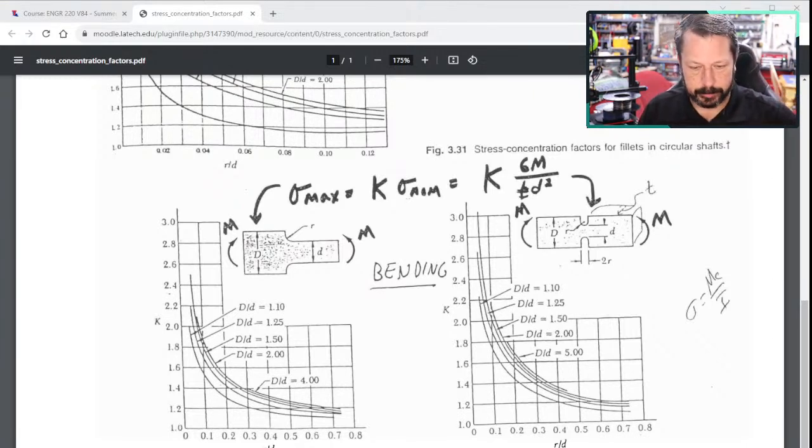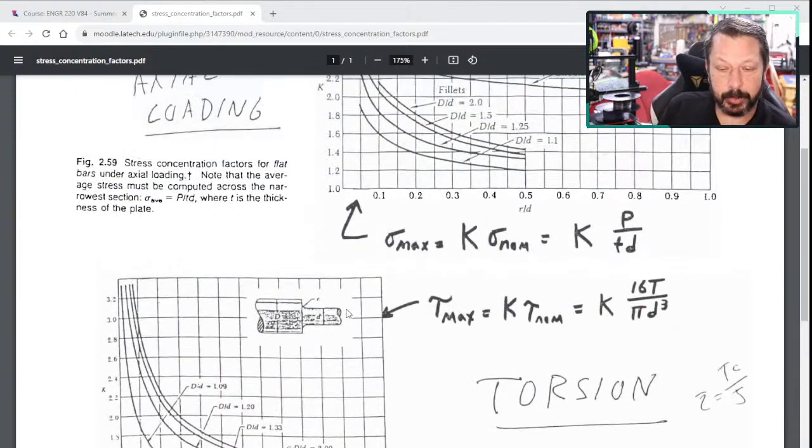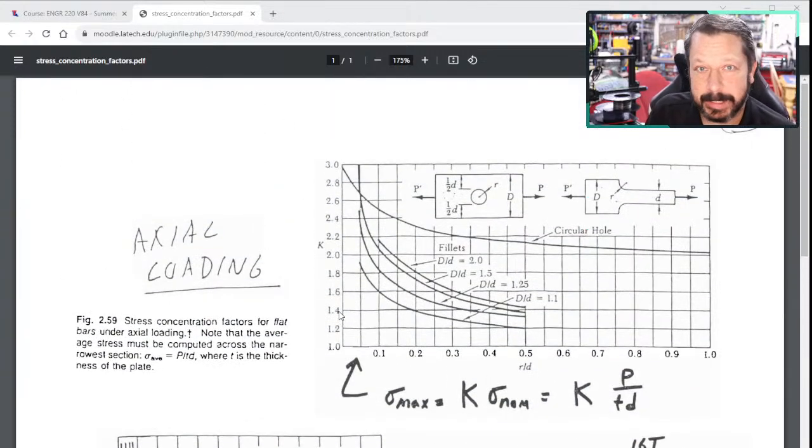All right. So we'll start over. What we're talking about today is stress concentrations. I've already pulled up a chart. You've looked at it, but maybe you don't know what it's talking about. What we've been calculating is the average stress in a bar or a plate or a bracket, a rod, a beam, all these different elements. When we calculate the stress with sigma equals force over area, or one of those equations we've used, that calculation gives us an average stress.